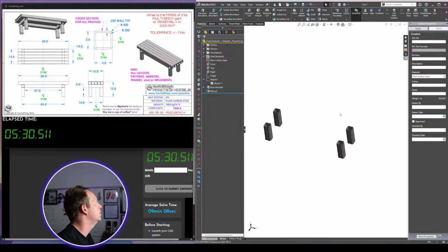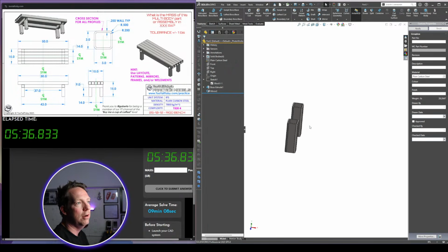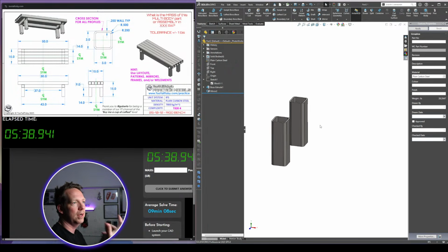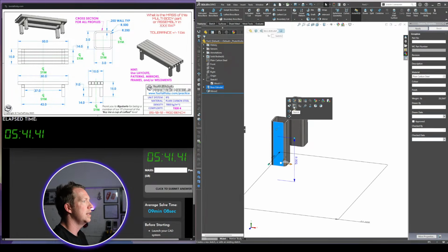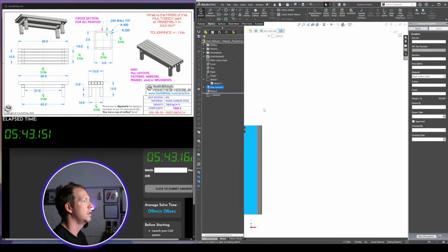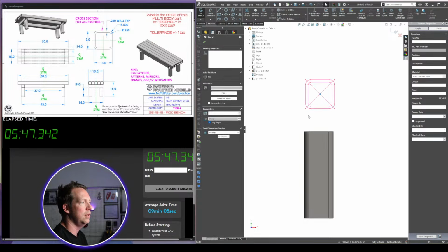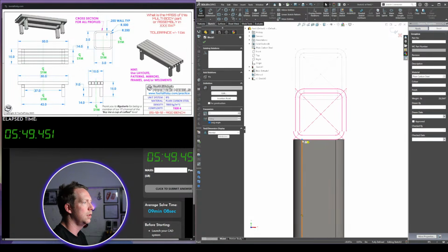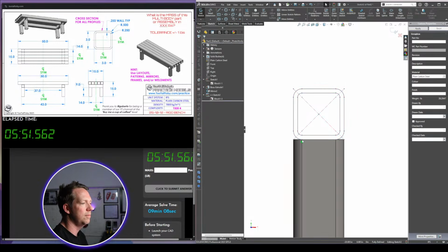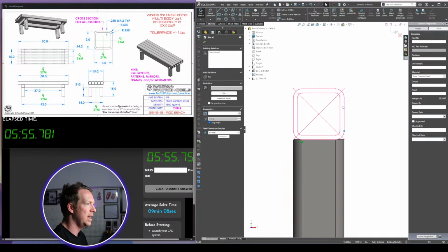And then we can see on the next level there are another couple of parts that are joining it. Now what we can do, I have that block on my clipboard. I can start another sketch here on this face, and I can Control V, and it's going to bring that block in, and I can just drop that block there. That's going to fully define it, even though I can still rotate it.